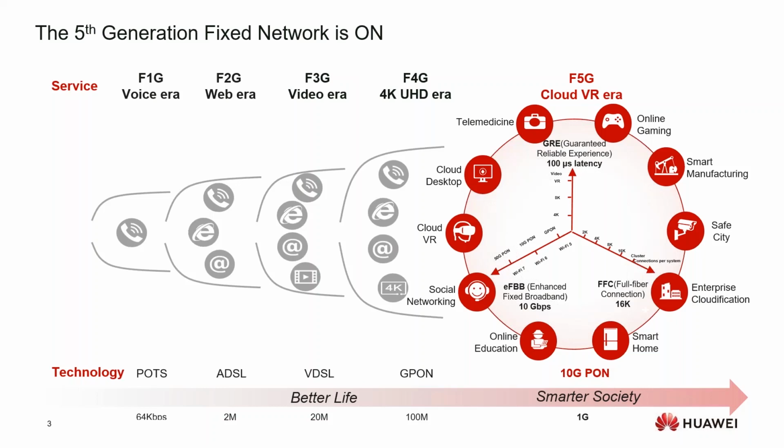Afterwards, as the bandwidth was limited, we got the third generation, represented by fiber extension and shortening of the copper loop. We got different technologies on twisted pairs, with multiple options in that generation: VDSL, VDSL2, vectoring, super vectoring, etc. Based on a network architecture of fiber to the curb or fiber to the node, the copper line was shortened to hundreds of meters to reach higher bandwidth, at tens of megabits level.